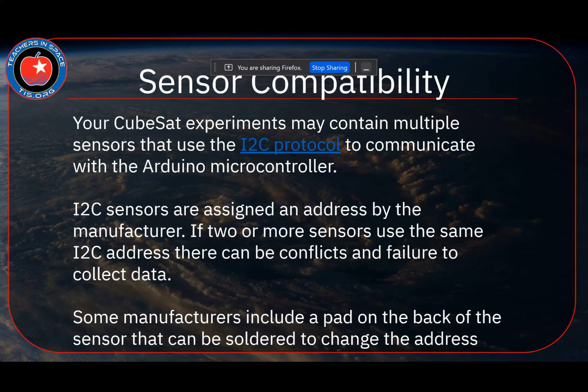And what it turns out was going on, and this is a common issue that seems to happen with every accelerometer / gyro and SD card reader. I've had this happen now with multiple different brands from different manufacturers for both the gyros and the SD card readers, where it turns out that for whatever reason, they always seem to have the same address.